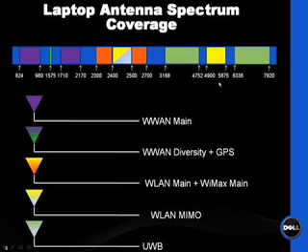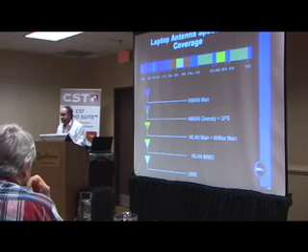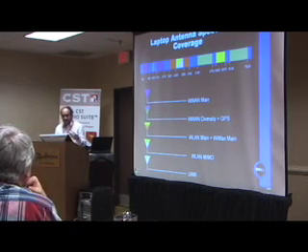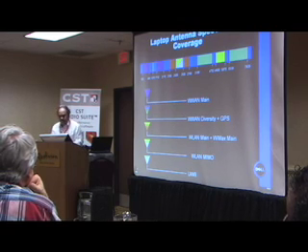And now we are also adding MIMO so that you can also use 802.11n. Apart from that, in the wireless LAN antenna, nowadays we are also putting a WiMAX feature so that it can be used for any far range. WiMAX frequencies are like 2300 to 2400 and also 2500 to 2700 megahertz range. So that is just 3 wireless LAN antennas. Usually WiMAX is for main and aux. MIMO we normally don't put that.